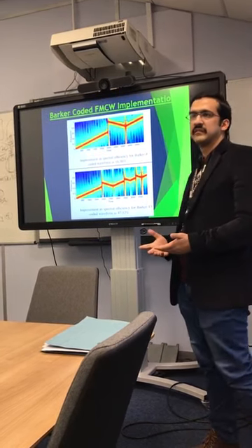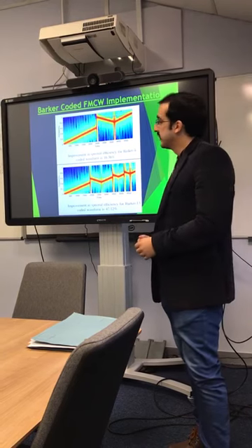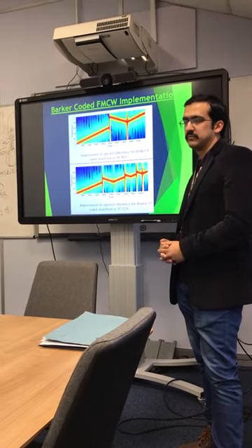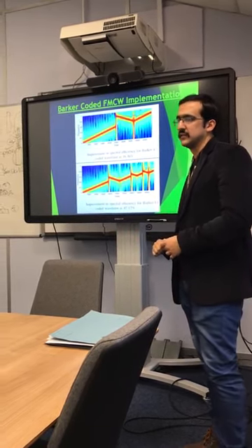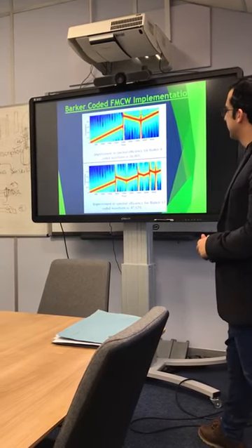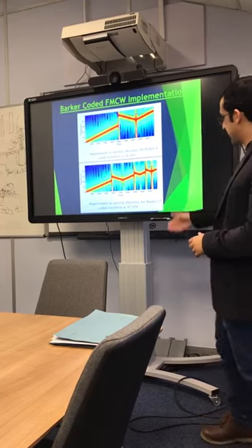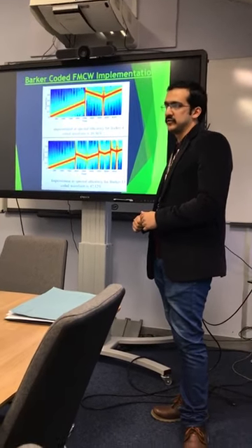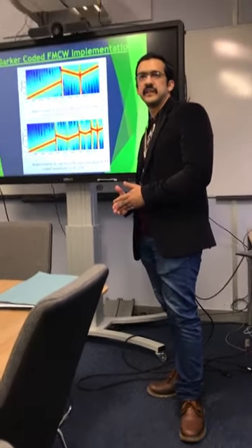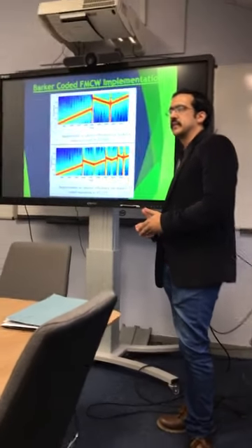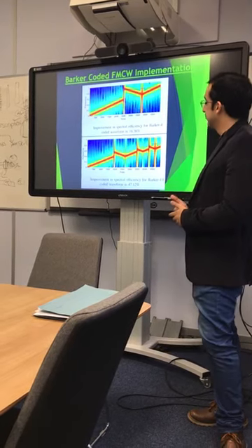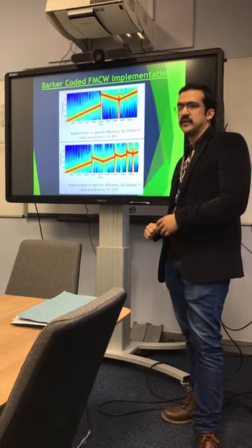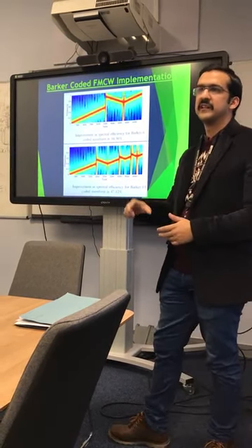So as you know, bandwidth is a very important and very costly resource. So compressing the bandwidth is very important these days, especially for state-of-the-art commercially available SDRs. So in that we have shown that we can get improvement in the spectral efficiency for barcode 13 of up to 47.12% at the cost of a very minimal decrease in the range resolution. As you know, there is a linear relationship between the bandwidth and the corresponding range resolution. But we have shown that by getting this 47% improvement in the bandwidth, we get around 20% degradation in the range resolution.